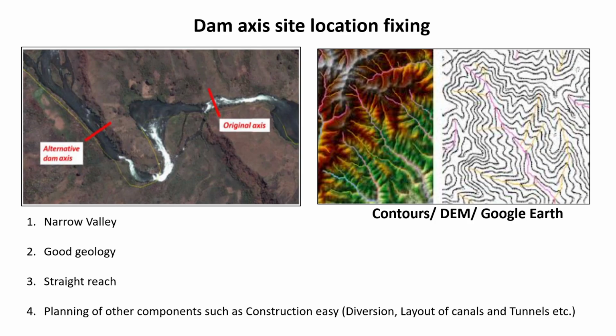Based on the field visit, we can observe the geology, site conditions and river characteristics and so on. At the field we collect data regarding field conditions including geology. Using computers and the latest technology such as digital elevation model (DEM) and other satellite data, we can generate approximate contours of the site to compare among the different alternative locations of the dam.